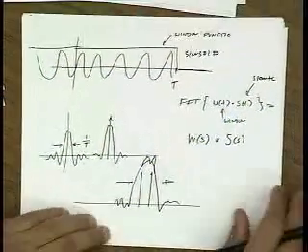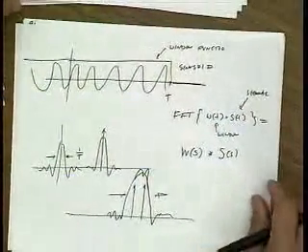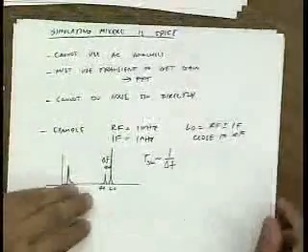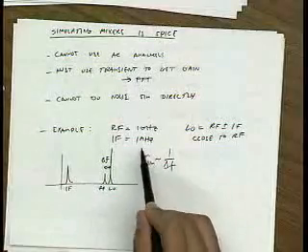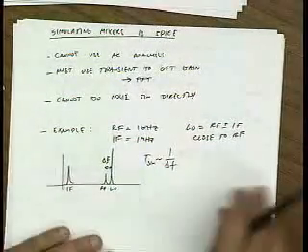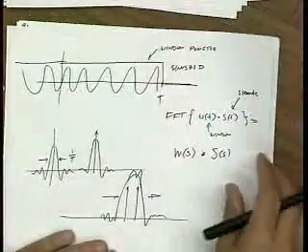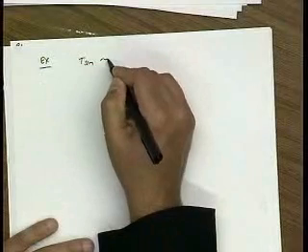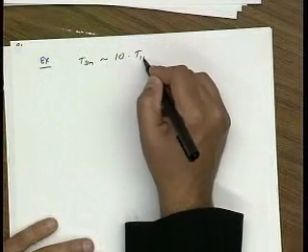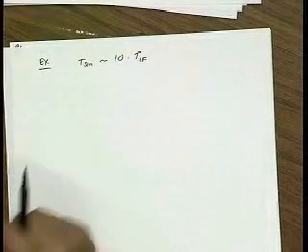So that means that coming back here to our example, we need to run, let's say, at least a simulation that's 10 IF cycles, right? So for our example, I want a simulation time t of roughly 10 times the period of the IF. Okay?